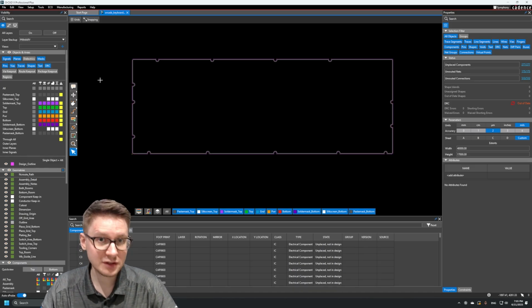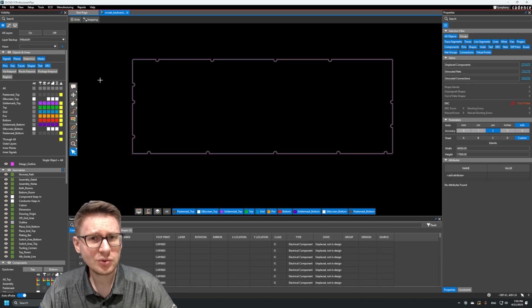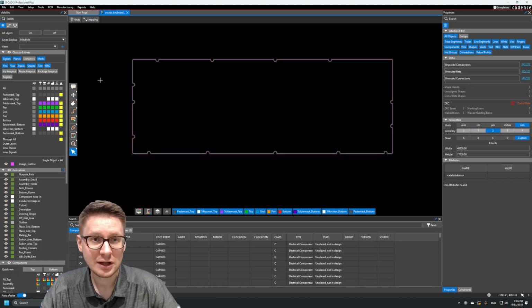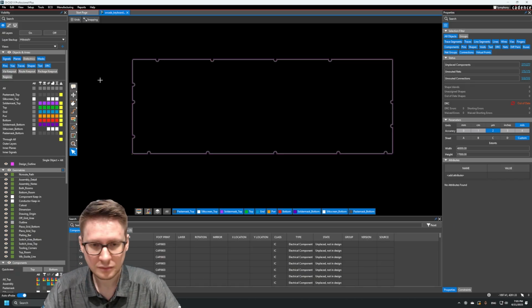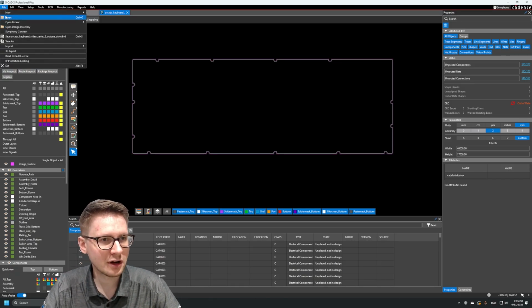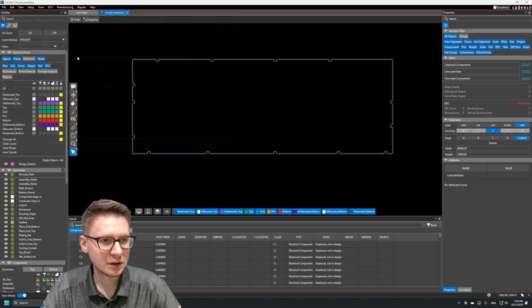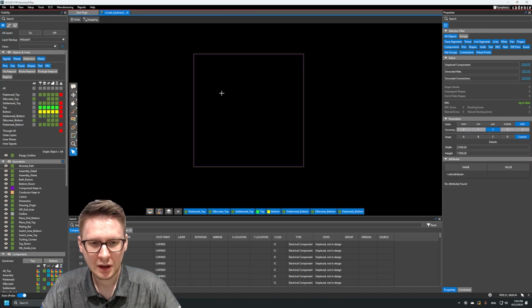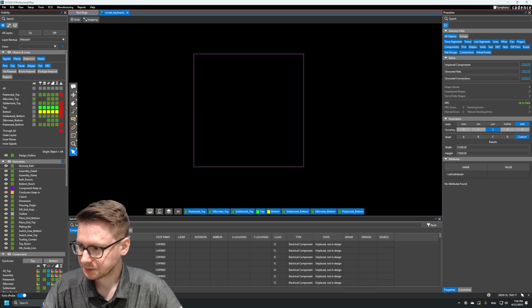Now what we're going to do in this video is actually draw it from scratch using the built-in functionality of drawing a board outline. The reason we're going to do that is just so that you can see, if you don't have access to a mechanical CAD tool, you can also draw some pretty complex outlines in OrCAD X. So let me go ahead and open where we left off in the previous video, which is this one right here. And what we're going to do is transform this outline into the one that you saw before.